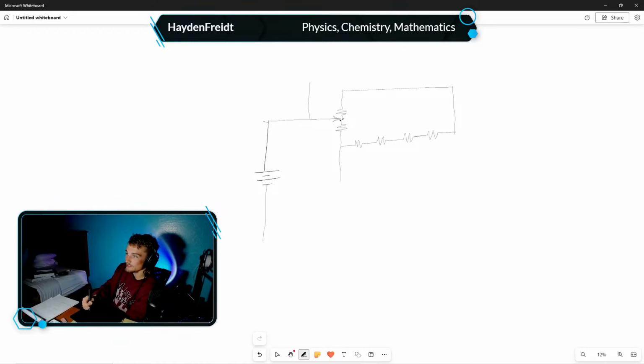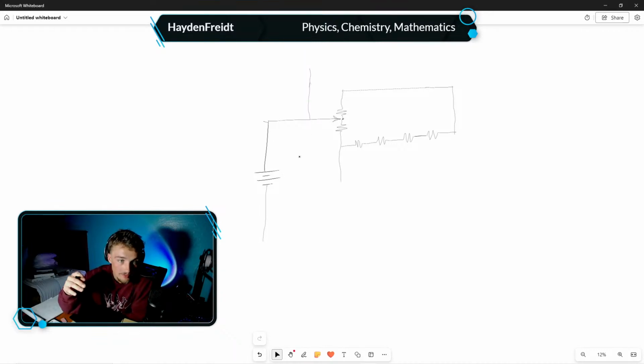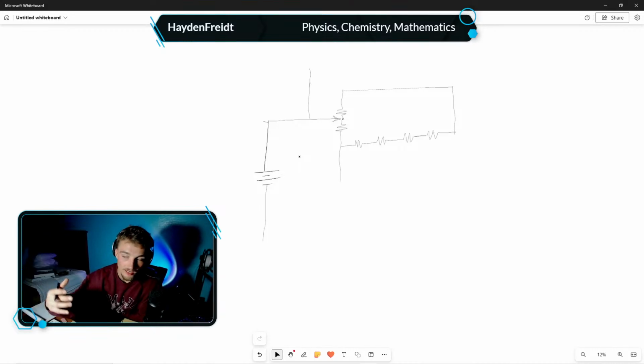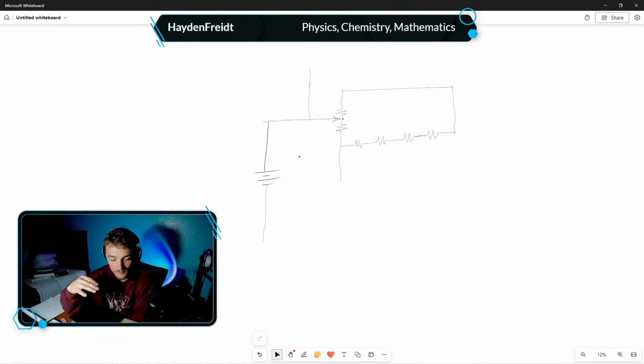Okay, and again, this is my potentiometer. So up here we're going to do a voltage dividing circuit for the purpose of supplying my LEDs. As of right now, I'm going to use an 8-bit LED segment display. I think that's what you would call it. That's what I'm going to use for the indicator of my supplied voltage for my voltage supply. But right now I'm just going to light up LEDs because it's going to be much easier when doing this prototype design before I do the actual circuit.